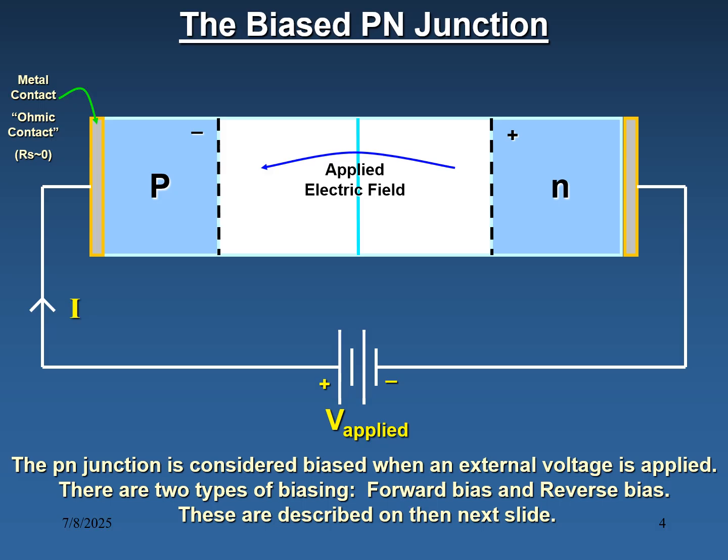In the forward bias condition, we know that the holes are majority charge carriers in P type, and electrons are majority charge carriers in the N type. The battery positive is connected to the P type. Both have positive charge, and the same charges get repelled. Repulsion occurs. In N type, the electrons have negative charge and the battery terminal is negative, so both repel. So these electrons move towards the junction. Here these holes move towards the junction.